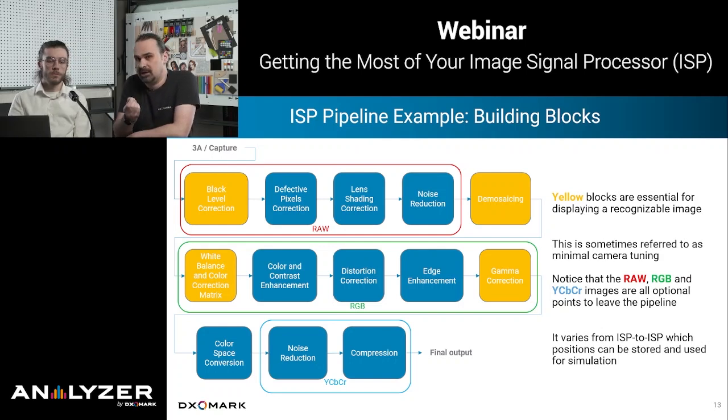So there is only one channel for each photosite, that depends on the specific color of the Bayer filter that is in front of your sensor. This is typically represented with a higher depth, a higher number of bits than the final image is going to be. And this is the closest you can be to the physical reality of your sensor and lens.